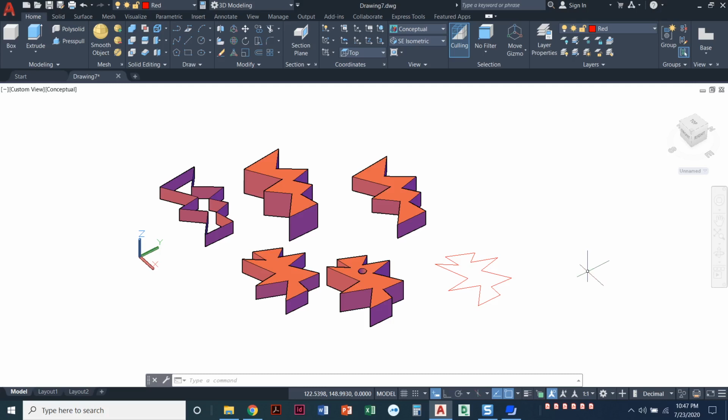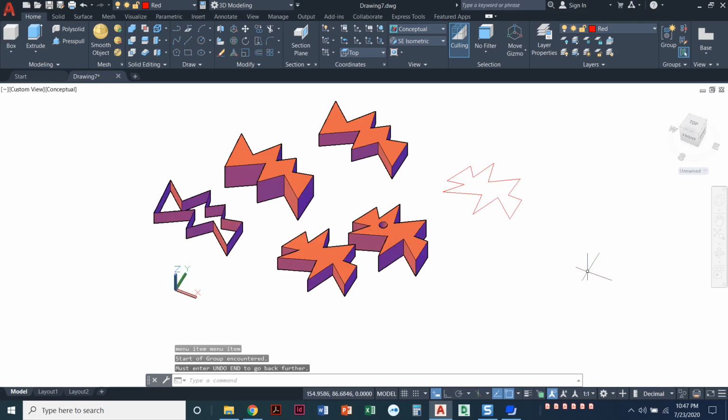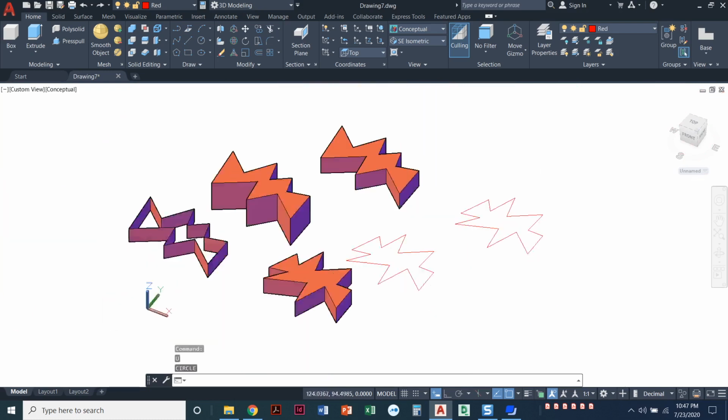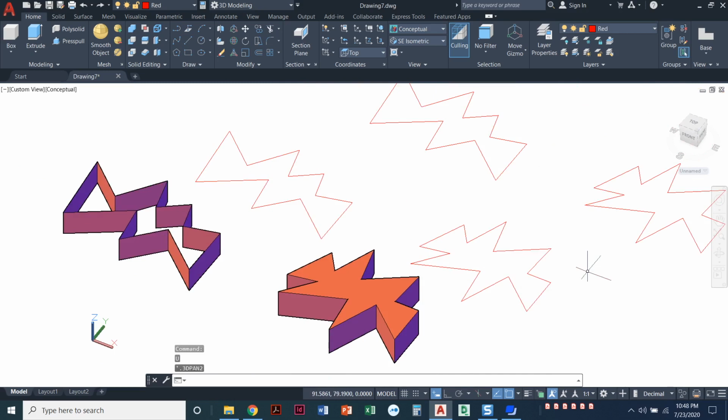I'm just going to do the undo command until I get back to the basic shapes that we first started working with. So enter will undo, and pressing enter will just repeat the last command. So I'm going to continue to press enter several times. We're undoing. I made a little cylinder here. If you remember, let's just take it to right here.